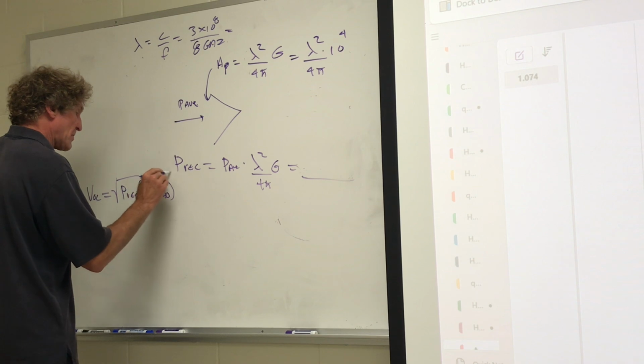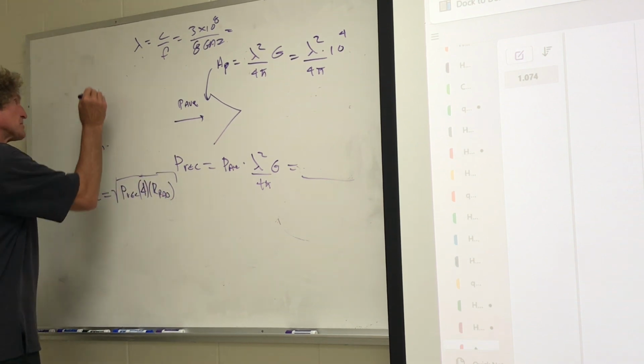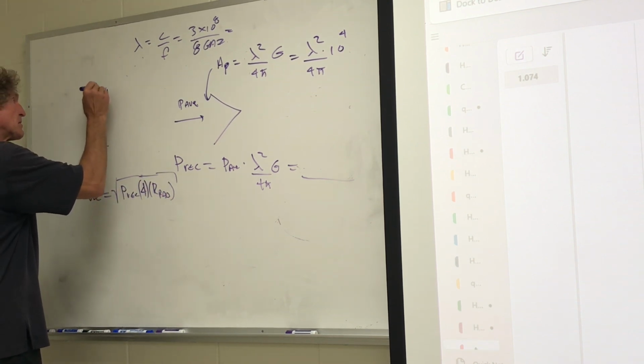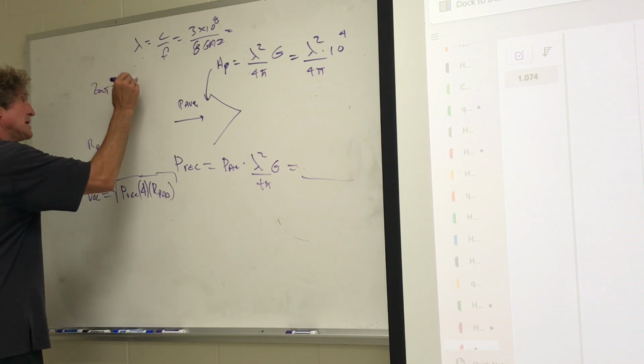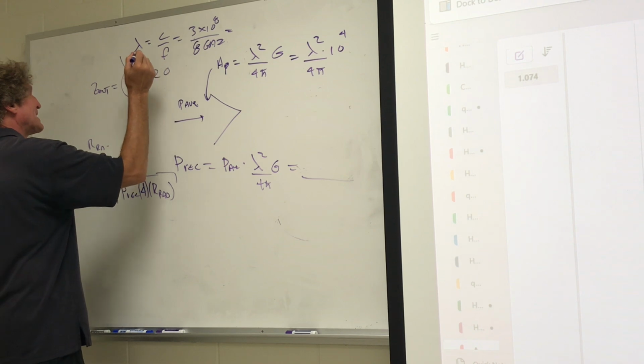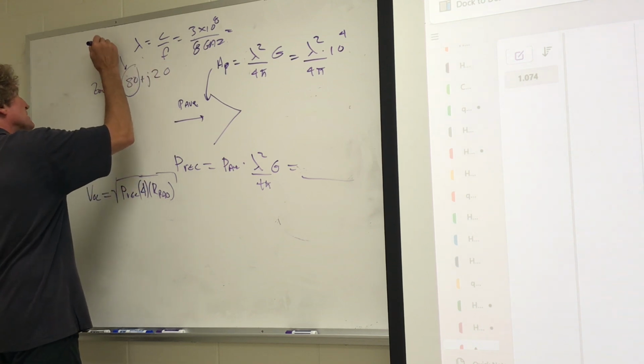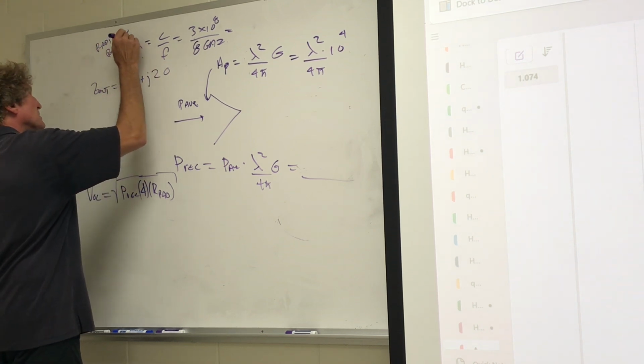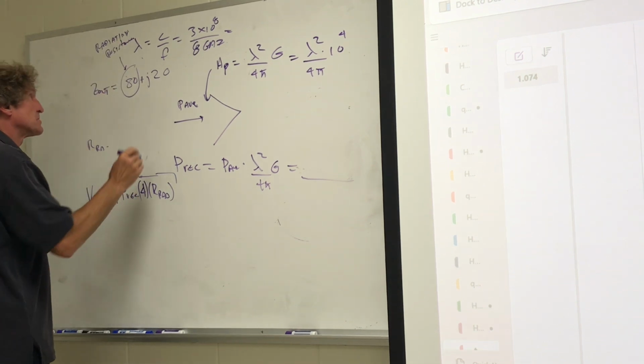And you can see R rad for that antenna was what? Because remember, Z antenna for the second one is what? 80 plus, isn't it 80 plus J20? The real part of the antenna impedance is the radiation resistance. And that's what goes here, 80.